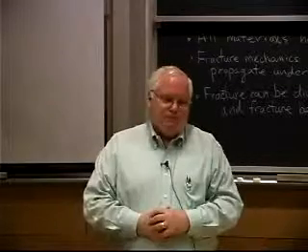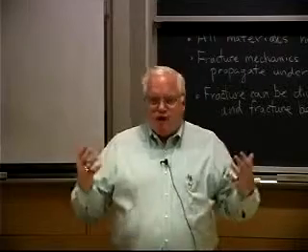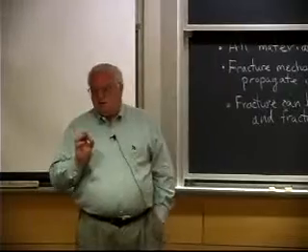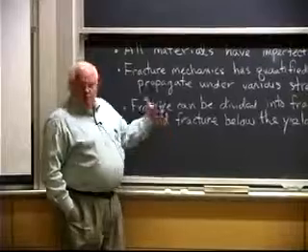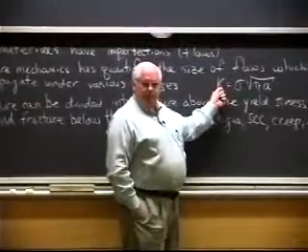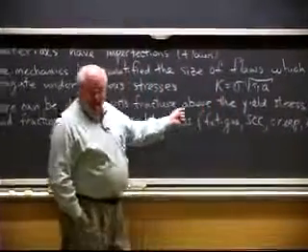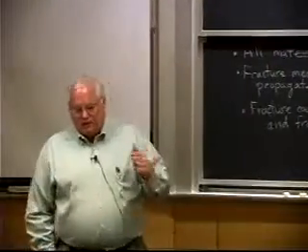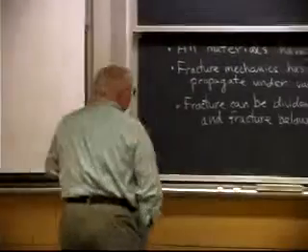If you actually went to an automobile or a plane, you would probably find dozens. If you did a very thorough inspection, you would probably find dozens of small flaws. Fortunately, if the material is ductile, it will be resistant. We're going to talk today about fatigue. It will be resistant to the propagation of the crack. If it has a lot of fracture toughness, remember that it's only when the stress intensity, K, becomes greater than the fracture toughness, K, of the material, that the crack is going to propagate catastrophically. And so if you have a high toughness material, it's hard to propagate cracks. And so you can tolerate big flaws.